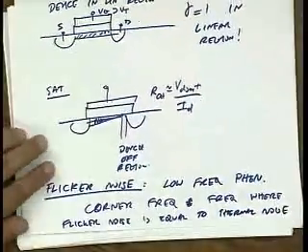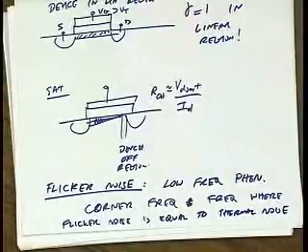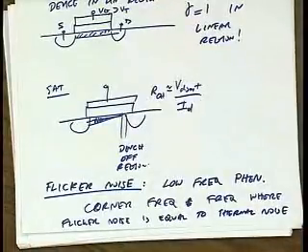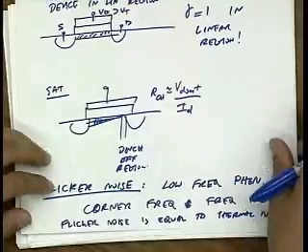In other words, if I told you a particular MOSFET has a corner frequency of 1 megahertz, that means that if you operate above a megahertz, the thermal noise dominates because the flicker noise has a 1 over f spectrum. If you're operating below a megahertz, flicker noise will kill you. Okay? And so first, we're going to deal with circuits that don't perform any frequency translation, like linear amplifiers. So a linear amplifier can't take low frequency noise and generate high frequency noise, and so the noise will be dominated by the actual noise at high frequency. And so flicker noise won't matter.